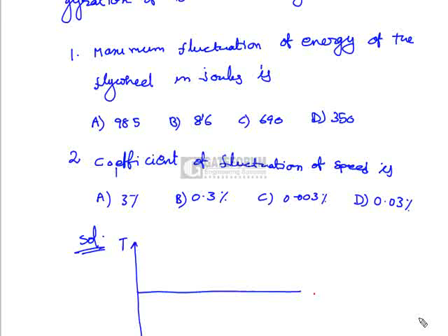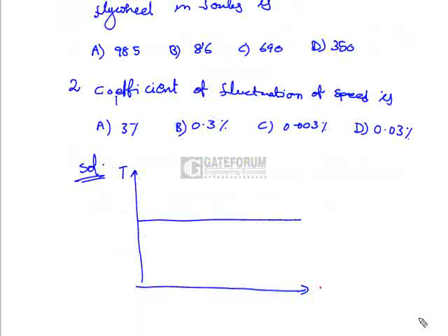and this is the crank angle. So turning moment on the y-axis, crank angle on the x-axis. Let us say this is the mean torque, and put the starting point as A. Now consider the second point, which has a torque of 295. This is a positive value. Just draw a line on the positive side. Let us say this is B